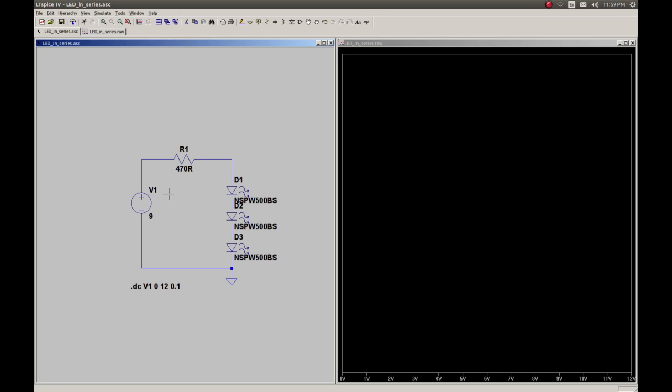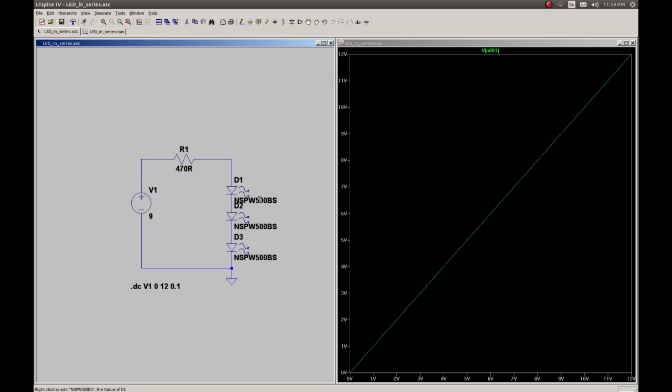If you want to see the input and output, you go near where you can find this red color pen-like structure, then you click, and here I gave a sweep of 0 volt to 12 volt, which is shown here. Then after the resistor, the voltage is shown, and you can see the curve starts to bend here.